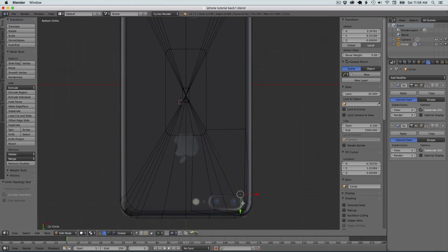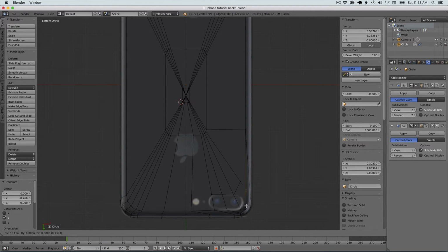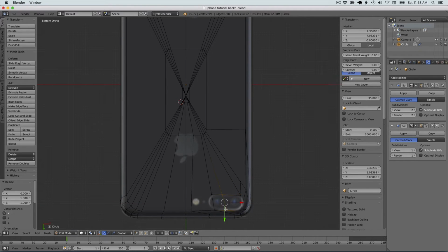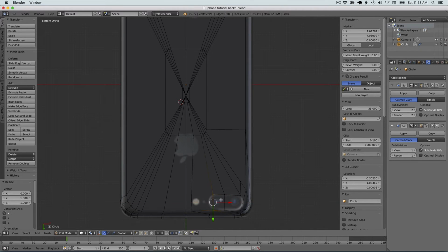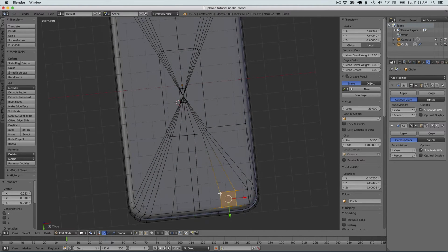And then, the reason I'm doing 4 is I want to get these guys out of the way here, and I don't want to cause a lot of chaos because I want to get those. So if I move this here, in fact, I'm going to do scale X 0 to get that nice and parallel. Same with these, scale X 0. And then we'll do scale Y 0, so we have a nice little box there. The reason I'm doing that is just so when we delete that out, which we'll actually do right now, we're not interfering with any of these weird lines, I think.